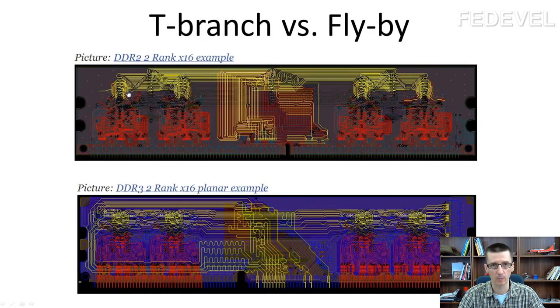That's exactly the reason why the distance between the processor pin and this memory pin needs to be exactly the same as the distance between the processor pin and this memory pin, and the same for this memory pin. When something starts here and the distance to all these memory chips is exactly the same, the signal will arrive at all these memory chips at exactly the same time.